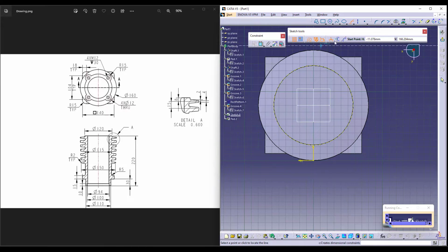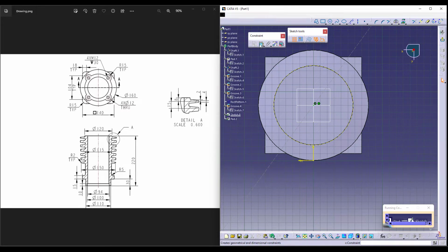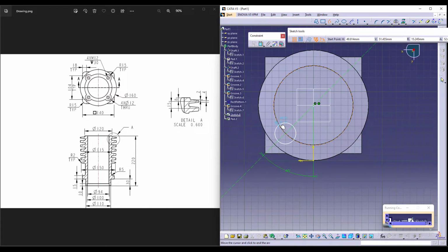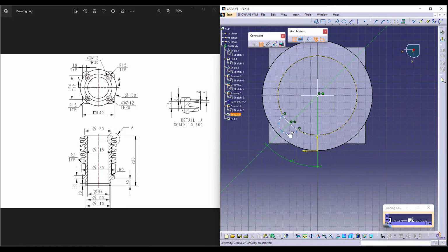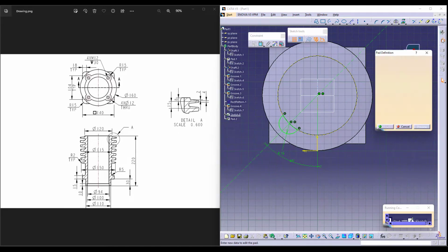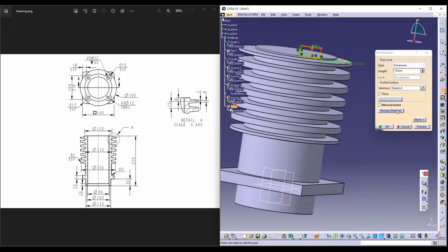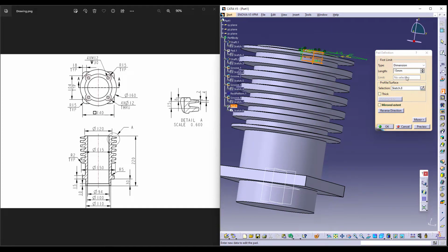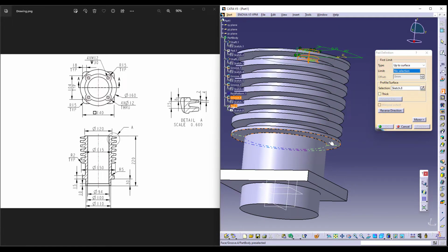Now, since the profile is actually starting from an angle, I'd like to use the angle first, give the dimensions and then proceed with the arc. So this is supposed to be 45. From here, let me try to take the arc and then another arc, of course, from the center to close this and give the dimensions for the same. This is 15. Let me try to maintain concentricity. I don't think it has taken it well. Okay. Now, this particular body is actually added till the end of the fit. So I can just directly select the surface and then say added up till here.